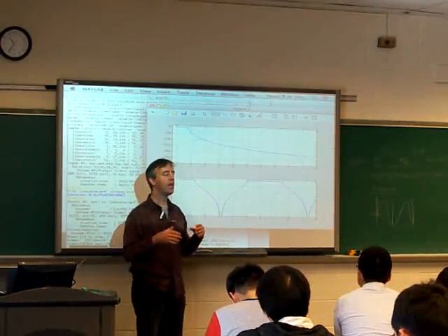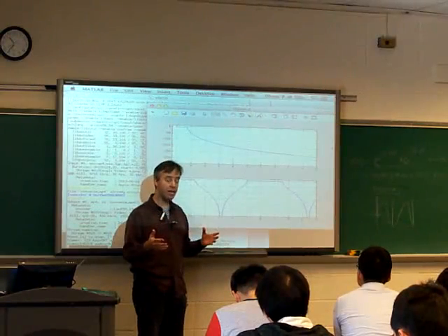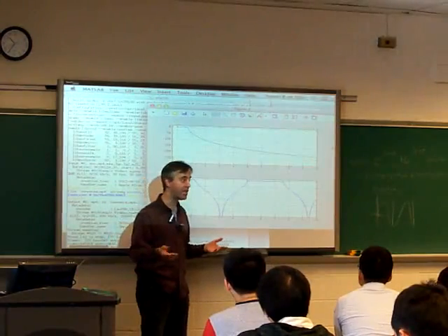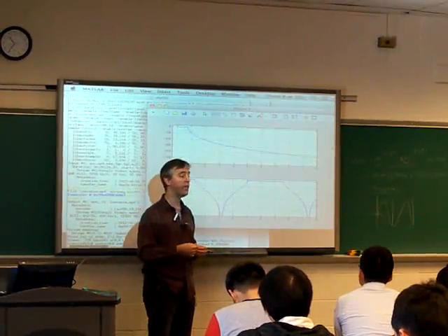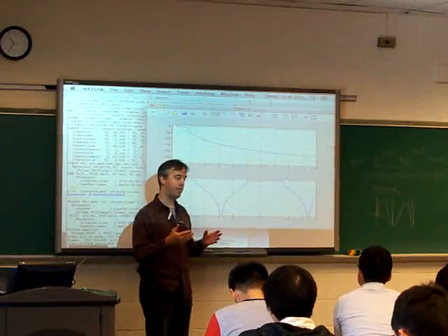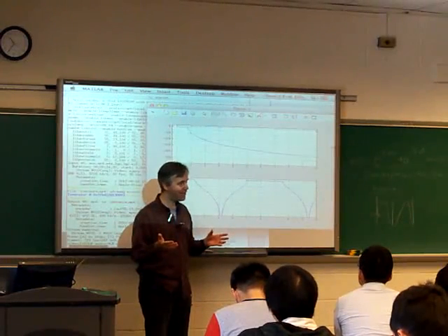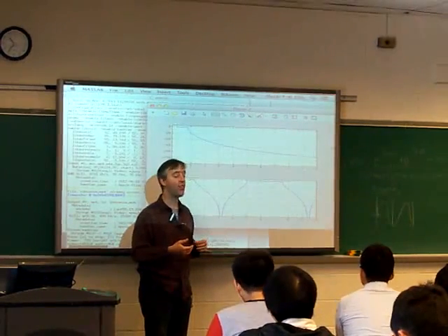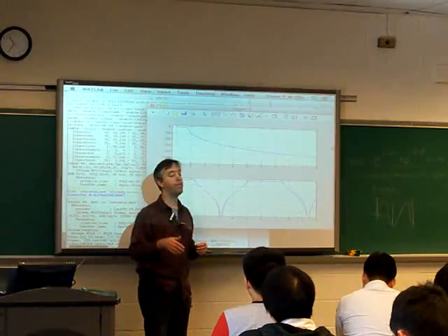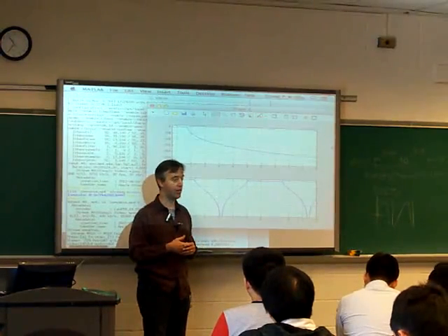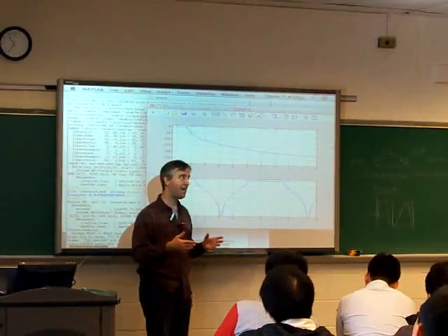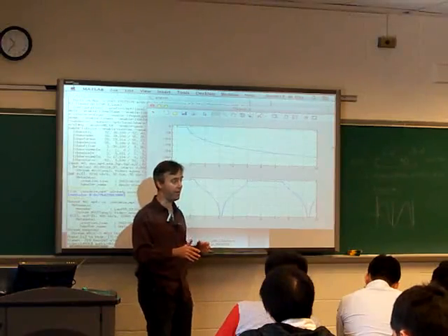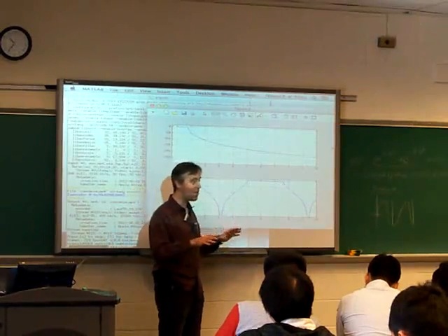2pi. So assuming we're starting with some kind of real world signal that can have any kind of frequency components in it, we have to care about them in the sense that if we just pretend they're not there, then when we do our sampling, we're going to get aliasing and we're going to be in big trouble. So we have to remember that they could be there, meaning that we have to filter them out before we do our sampling, which is not.